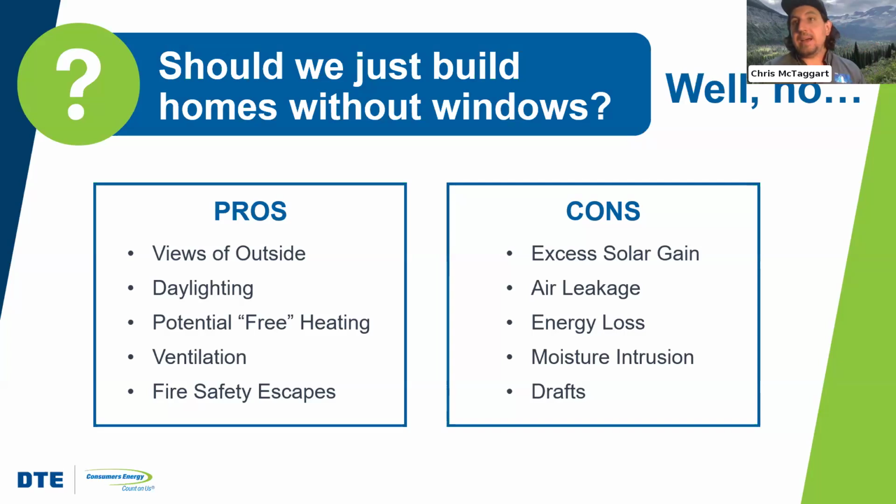Moisture, because my windows are more airtight, I also am not bringing in humidity from outside. And in the winter, I won't feel draftiness if the wind is blowing or if there's a big temperature difference, which drives the stack effect, something we talked about last week. Then having better windows are going to end up basically reducing those drafts.